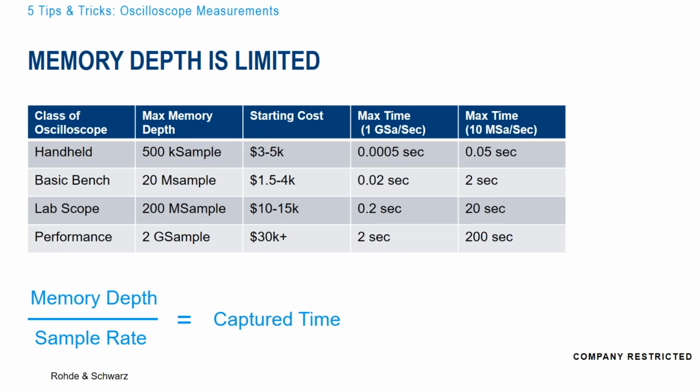A really common challenge that we see is in the automotive space. We'll see engineers, a lot of times mechanical engineers, say, look at this signal for 5, 10, 30 seconds. Because that seems reasonable when you're looking with your own eyeballs at something that's moving and physical. When we move over to the electrical space, it becomes very, very challenging to look at something for seconds. We're typically used to dealing with nanoseconds, milliseconds. So when we go to full seconds, that's a lot of data that we're having to capture. In some of those cases, they've actually had to invest in a higher deep memory oscilloscope to make some of those long measurements, even though it's a relatively low speed signal. So it's something to consider.